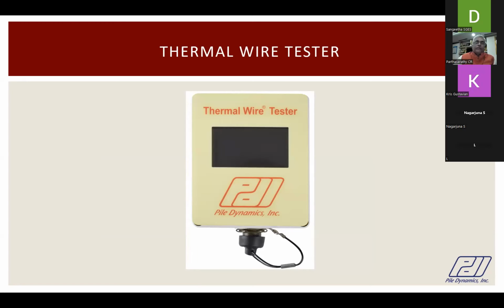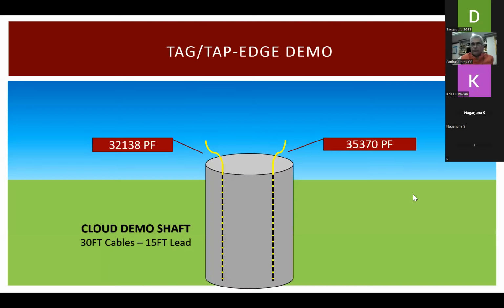And just before pouring the concrete, you are sure your wires are functional. If there is any problem in any of those nodes, you can always note it, and later on in the data processing, you can actually turn off those nodes. So PDI manufactures the wire with a 5-digit serial number for each of those wires, and you have different nodes for these thermal sensors. Okay.